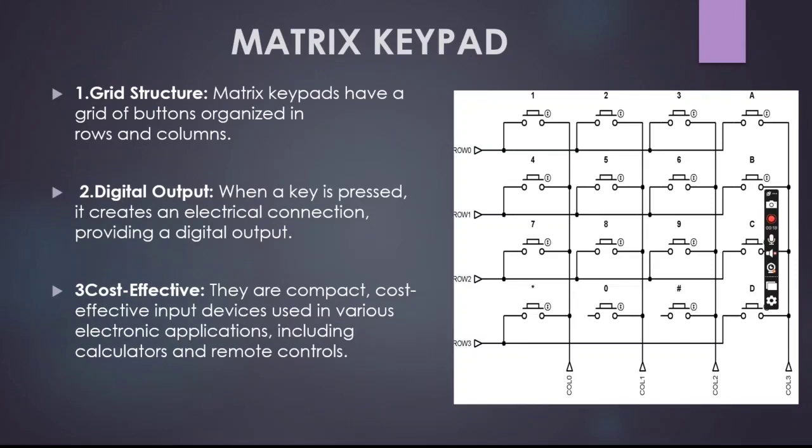This 4x4 matrix keypad has 16 built-in push-button contacts connected to row and column lines. A microcontroller can scan these lines for a button press.